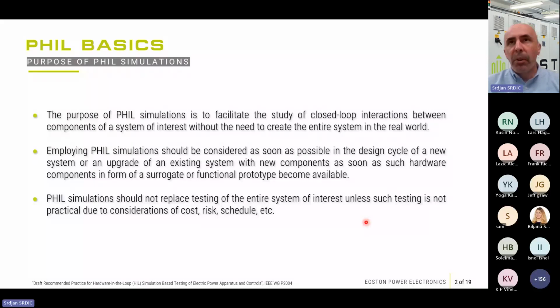The question is also when to do Power HIL simulations, and the simple answer is as soon as possible, which means that basically, depending on if you are simulating a new system or you want to simulate an upgraded system that you have already developed, then the simulation should start as soon as hardware is available of such prototypes, or as soon as you can start with the simulations of the new systems.